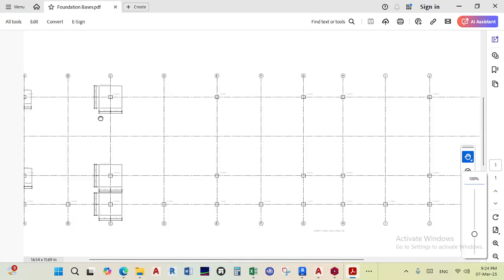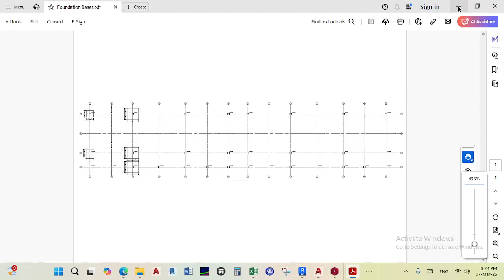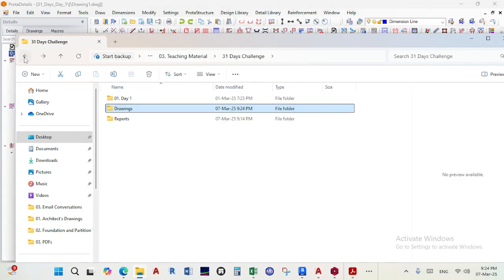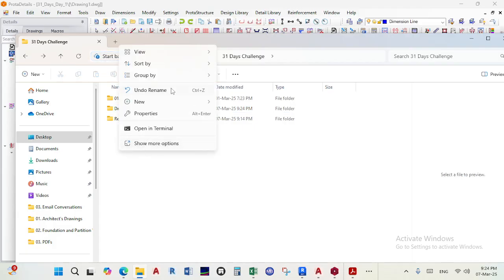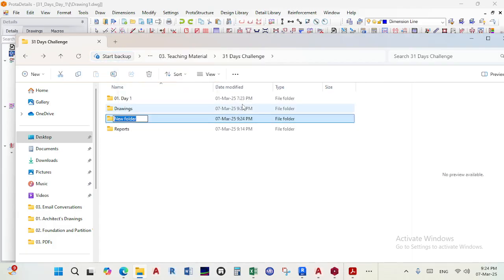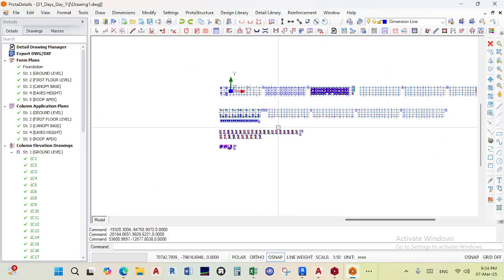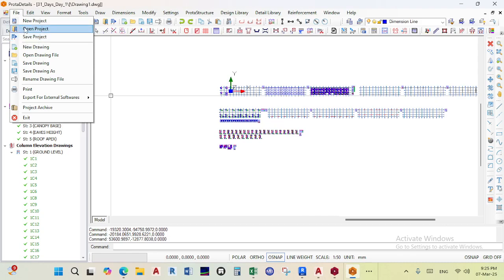For me personally, I would recommend you have your own template and then you send to AutoCAD. So how you send to AutoCAD is, in fact, let me have a folder here that says DWGs. How you export to and import to AutoCAD, you have all this information and you say export drawing. Here it says export. You choose the type of export and what file format you want to use.